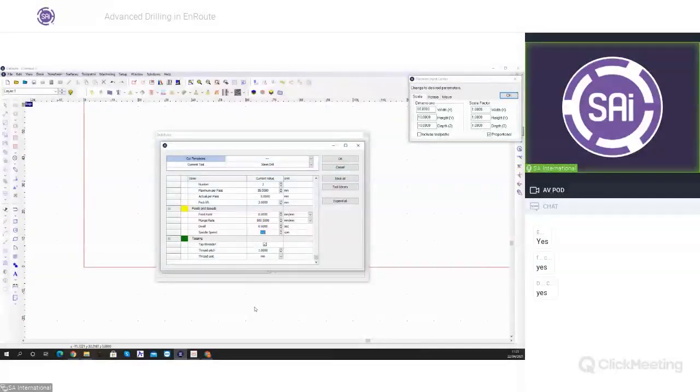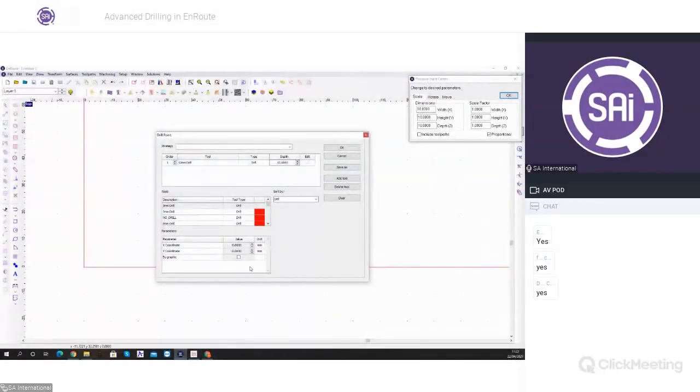And then once it's gone down to the depth that you require, it should also be able to reverse out in the same way. So it will have to rotate backwards while lifting up the tool. Otherwise, it will destroy the threads, of course. And yeah, basically, these are all the parameters that you can choose while drilling and all of the strategies as well.